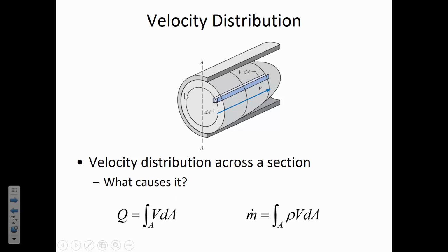So you can see here in a given radius what they've done is they've said, let's have some elemental area represent a section of our flow cross-section, and we'll find out the actual velocity at that particular point. And then if we did the same thing with all of the different elements that form the face of that flow area, then we could find the flow rate by integrating the varying velocities over those incremental areas.